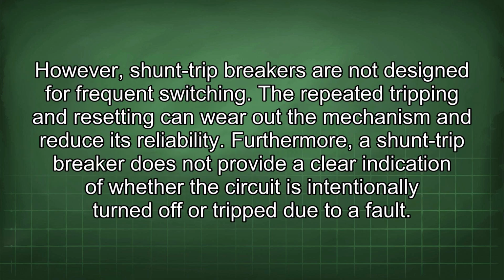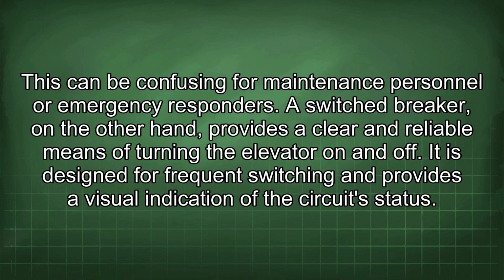However, shunt-trip breakers are not designed for frequent switching. The repeated tripping and resetting can wear out the mechanism and reduce its reliability. Furthermore, a shunt-trip breaker does not provide a clear indication of whether the circuit is intentionally turned off or tripped due to a fault. This can be confusing for maintenance personnel or emergency responders.